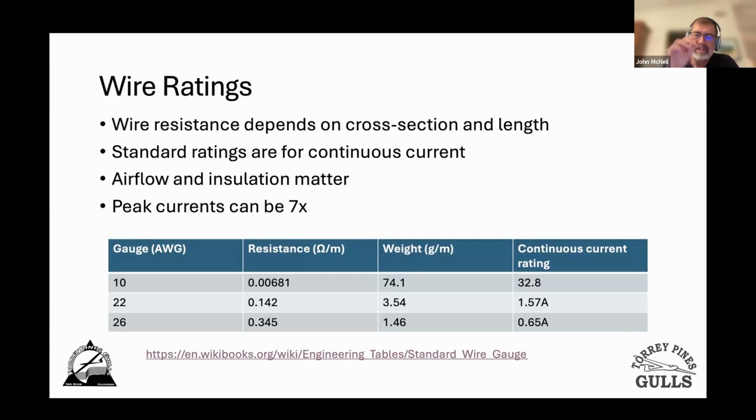If I put it on and one of them is a tenth different than the others, I'll charge it once and fly it again. If that happens twice, that battery is done for me. That's for non-critical applications. For critical applications where I'm really pushing the current, I won't even go that far. Puffed packs are out.